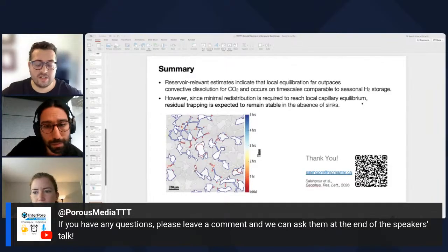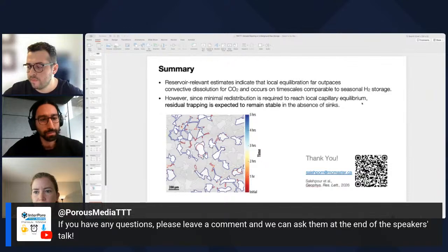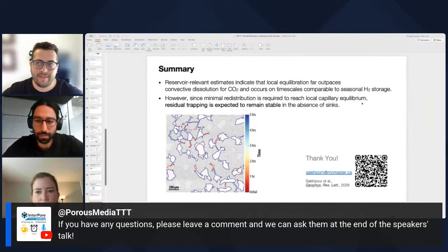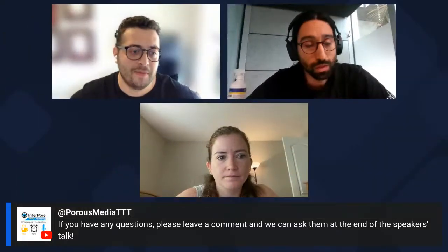It was one of the challenges early in the experiments. When I started the experiments at this resolution, we noticed vibration even when someone was walking around the setup. So we were lucky enough to have two labs. One of the labs is in the basement of a building, and the floor is concrete. So we moved the setup there, and we made sure that there's no vibration in the experiment. So we used that lab to eliminate the vibration in the system.